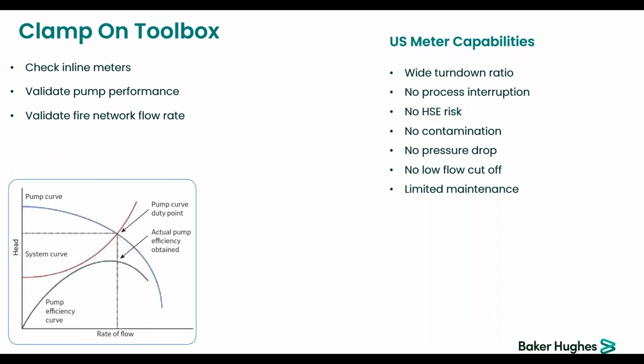You've seen also that we have, I just want to show some pictures. So we have this kind of portable. This portable is very handy if you have to assess a pump. For instance, on your plant, you have many pumps, and you know that the pump is expected to deliver a certain height at a given flow rate, but are you sure it's still delivering what it is designed for? So if you know the pressure, you need to know the flow to ensure that the pump is delivering as per its original specs.